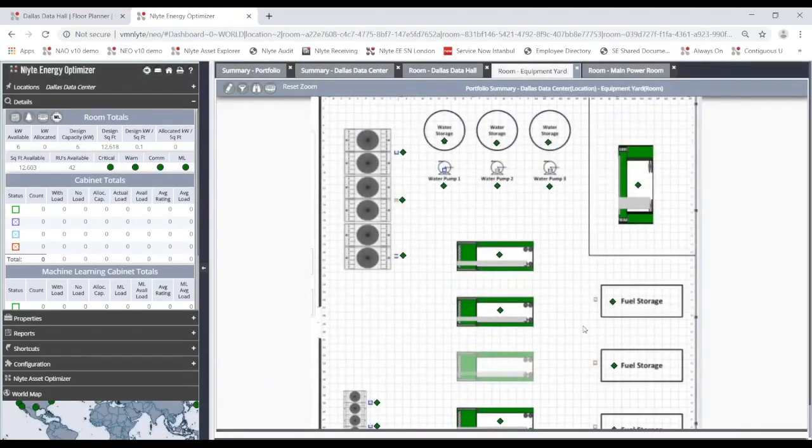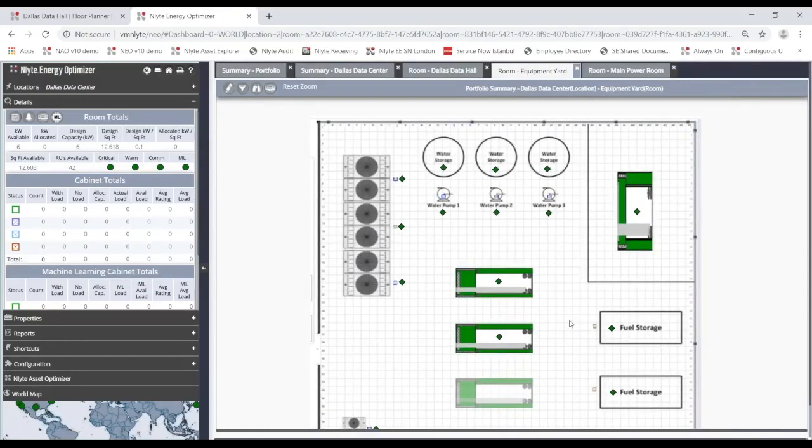So basically any meter that you have that's on the network, we can monitor it, number one. And number two, it gives out information that we can collect over our standard protocols such as Modbus, BACnet, SNMP, Modbus TCP, OPC, XML, JSON, and a few others. Those are the main protocols that we see to be able to monitor the different types of devices that you may have in your data center, in this case, in your facility.